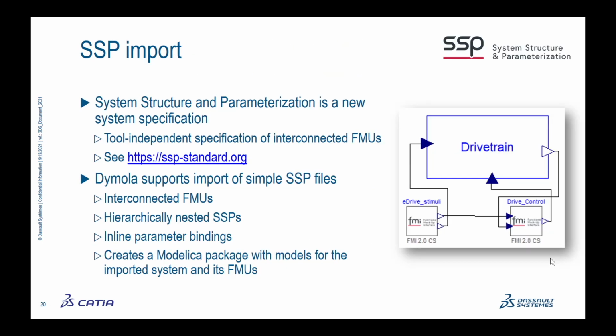We now have early SSP support, System Structure and Parameterization. So you can import an SSP file that contains interconnected FMUs and hierarchical SSPs, and also some simple inline parameter bindings. And it creates the corresponding Modelica model that is then ready for simulation in Dymola.